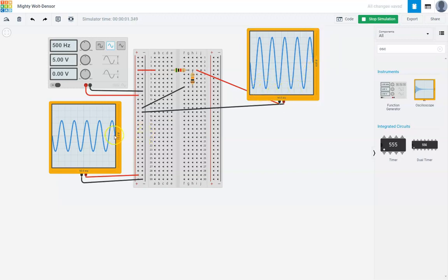Now notice that this one looks smaller than this. Just be careful, because this is telling me that from the top to the bottom is 4 volts, right? The time axis from here to here is 10 milliseconds, and the overall y-axis here is 10 volts. Here the overall y-axis is 4 volts, hence the output actually looks larger. So just be careful. That is one quirk of this thing you need to be careful about. Okay, so here's a simple voltage divider using TinkerCAD.